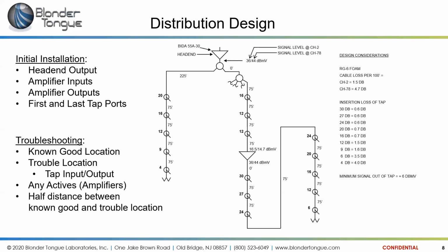Are there any cable TV amplifiers or other devices with AGC to adjust for temperature differences or possible overload? Yes, there are cable TV amplifiers. They're primarily what they call hardline amplifiers for outdoor use, in the big extruded aluminum housings. Not anything that Blonder Tongue has, but they are available on the market.